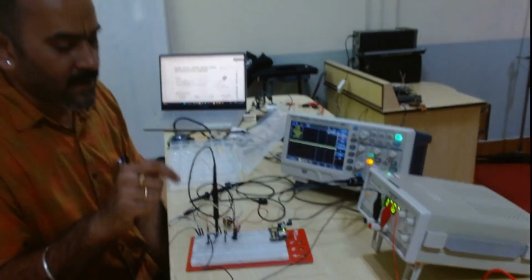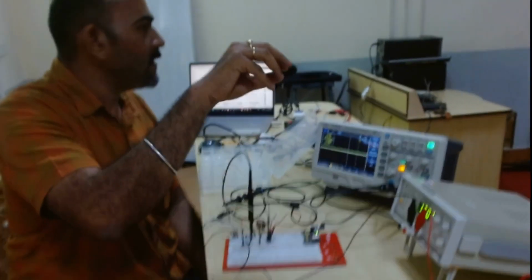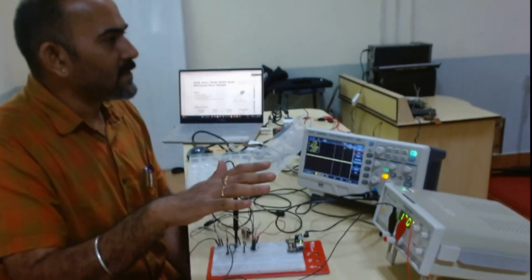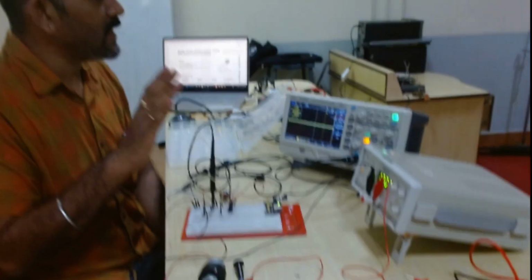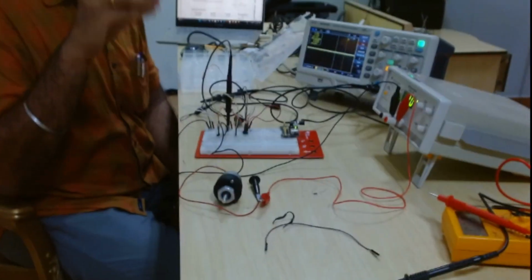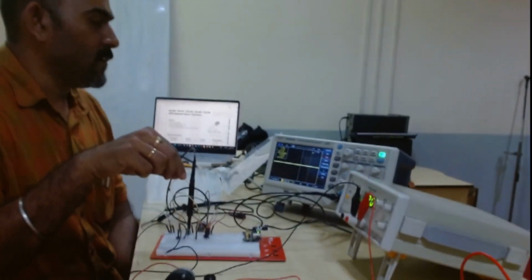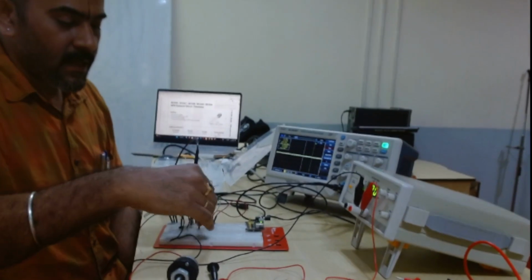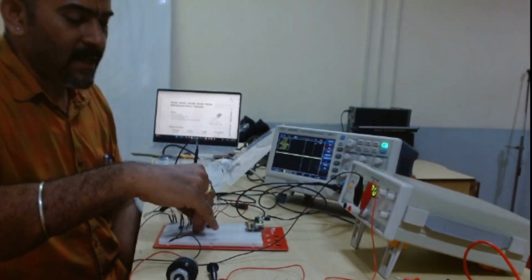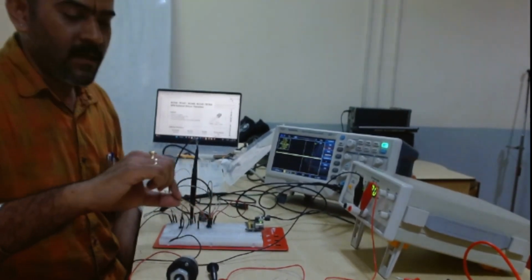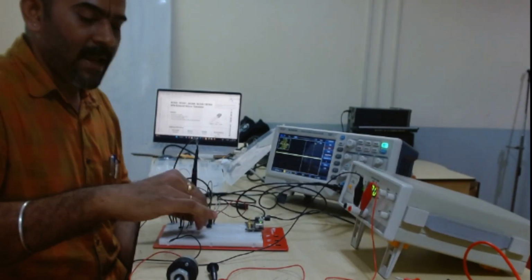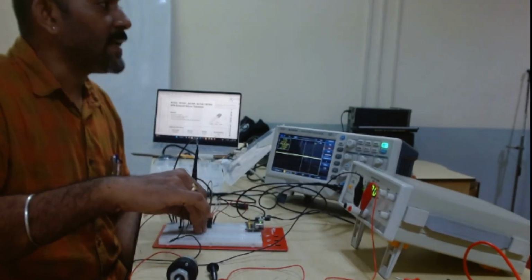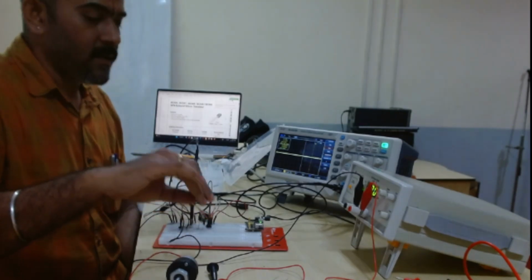So this is what it takes. Even though it is a very small circuit, normally works. Because we have very few components here and generally it tends to work as intended. But there can be issues even with this component. One more example I'll give. I'll just remove this. This is a ground connection for the capacitors, timing capacitor. I'm removing that wire, indicating an open circuit there.